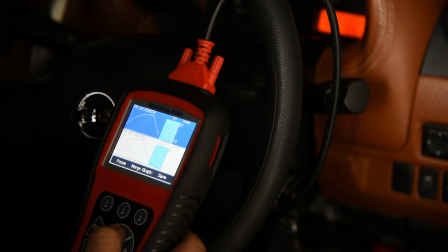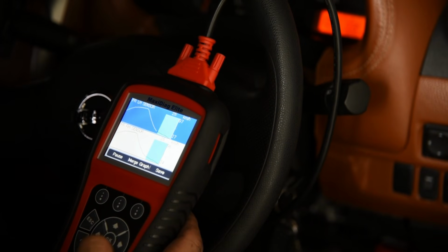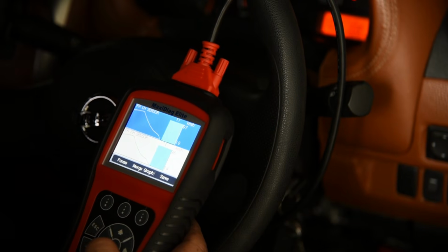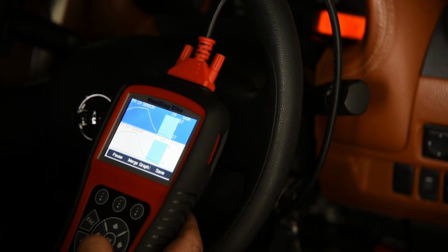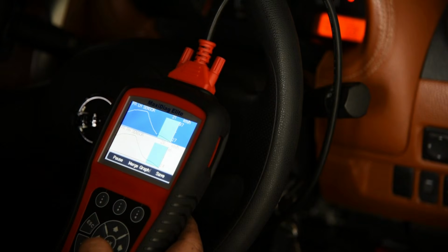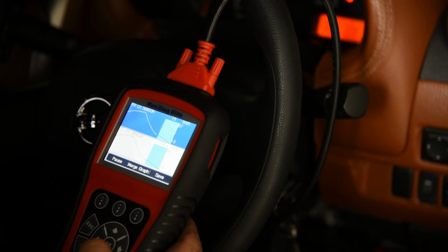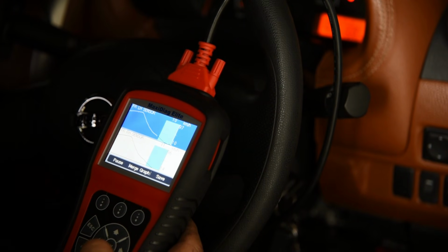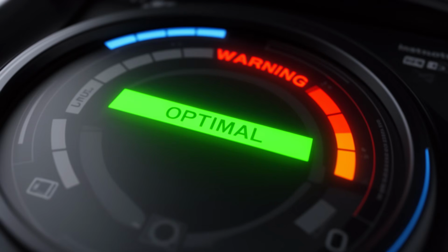While the sensor dries, reconnect your OBD2 scanner and clear the long-term fuel trim data. This step is non-negotiable. The ECU has been storing an additive correction factor, the positive fuel trim offset we identified earlier. That was the correct compensation for the fouled sensor. With a clean sensor reinstalled, that correction is no longer appropriate. If it is not cleared, the ECU will continue to over-inject fuel based on a correction that no longer has a physical basis. You will have a clean sensor being overridden by stale, adaptive data.